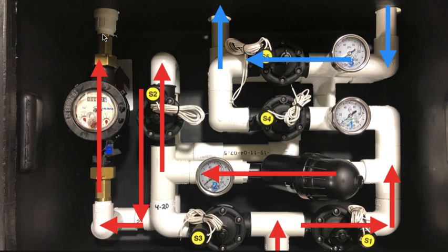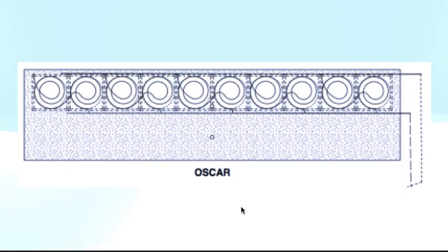Now what's going on every time this doses, the pump is pumping more water than the coils can get rid of. So if we look at this picture of a drain field really fast, so let's just call this one down here, this one below the supply line. When the pump kicks on, this tubing can only get rid of water at a certain rate.